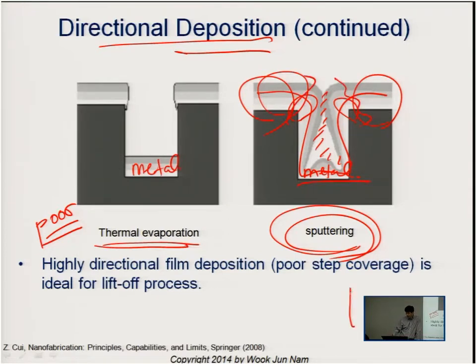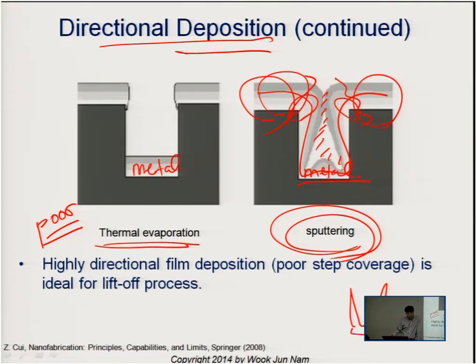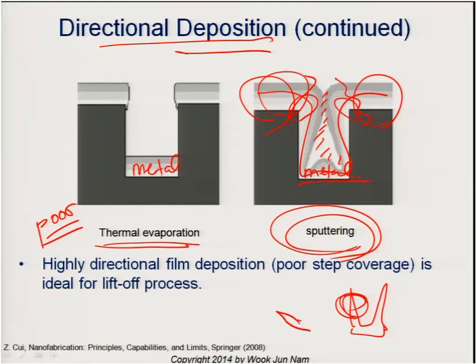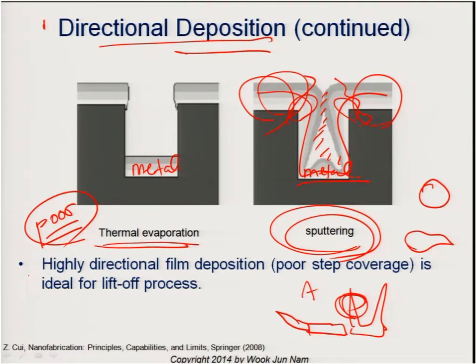So you may have this kind of rabbit ear, and sometimes in these small dimensions, the films just stick to the substrate. So your substrate from the top, instead of circular, has very strange structures. So in this case, the poor step coverage of thermal evaporation is a good advantage.